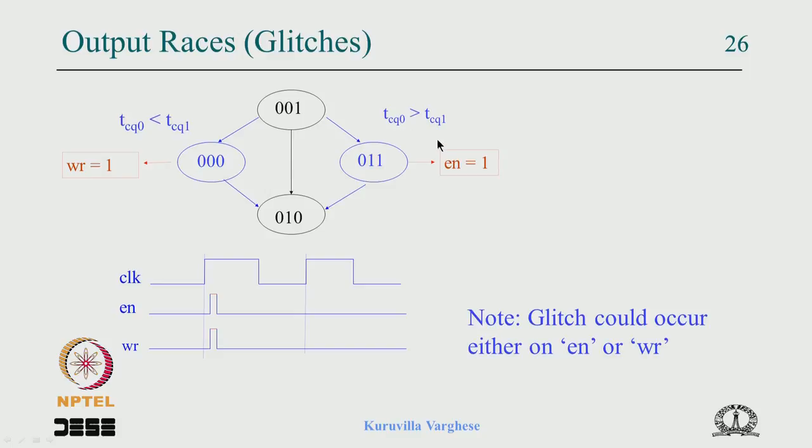You fabricate it, and everybody tries to fabricate on the same die very close together, but yet when you do the electrochemical processing, there could be a variation. But if you think again deeply, you see the problem has come because there are two flip-flops changing state. That is why the variation in delay is affecting.